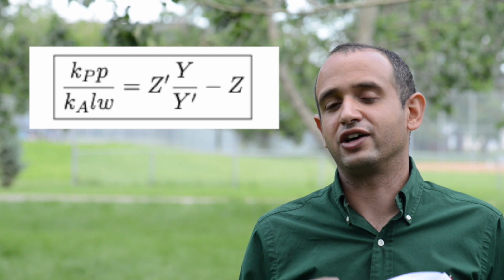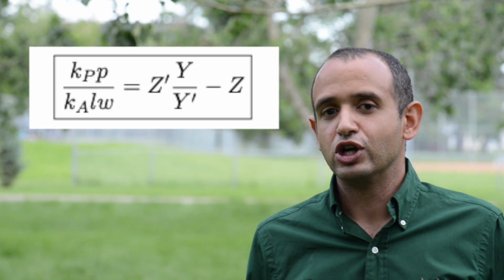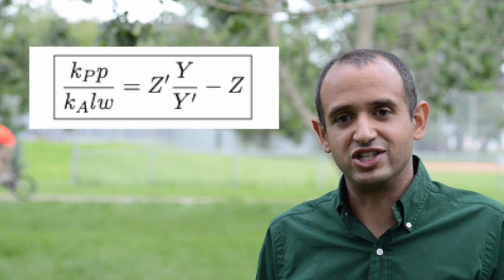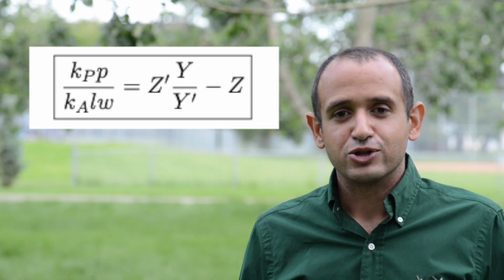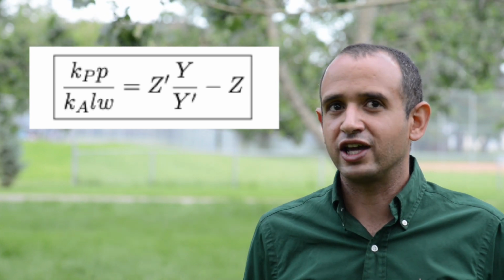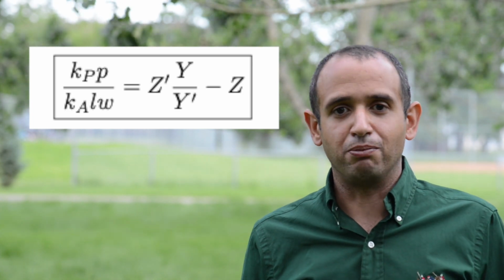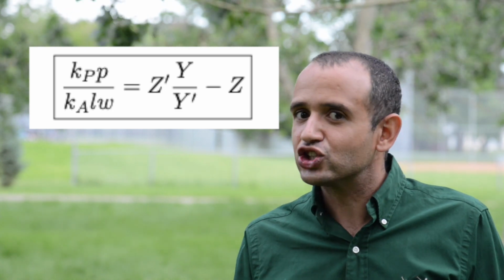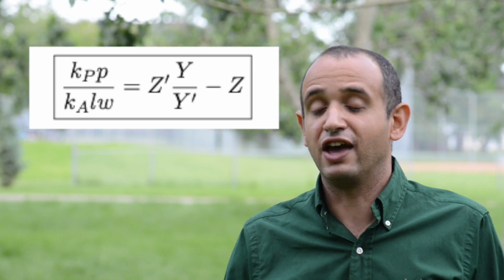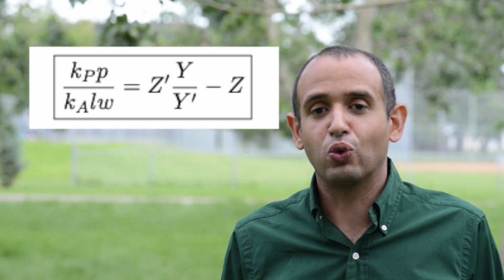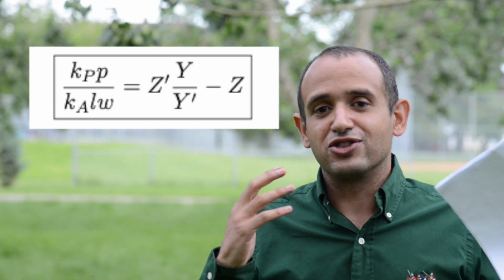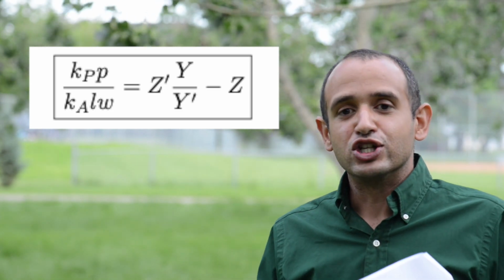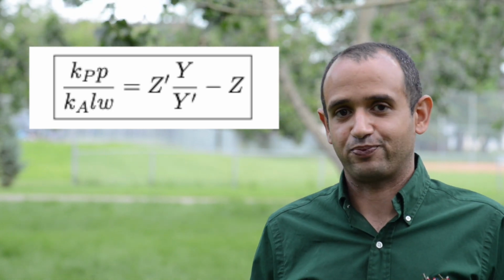What's interesting is what's on the left, specifically that P over LW. So what's P again? P is the table's capacity. LW is the table's normal area. So P over LW sounds a lot like, for example, if you have a 400 watt module with dimensions of 2 meters by 1 meter, that's essentially the module's effective PV efficiency if you multiply it by 1,000. So what we have found is that the optimal tilt is directly related to the module's PV efficiency.